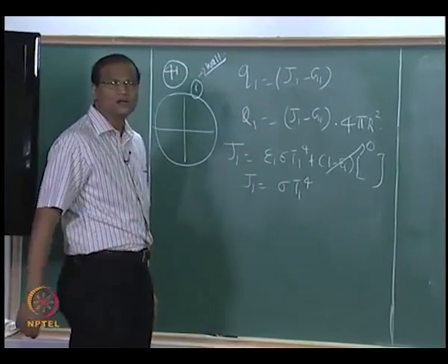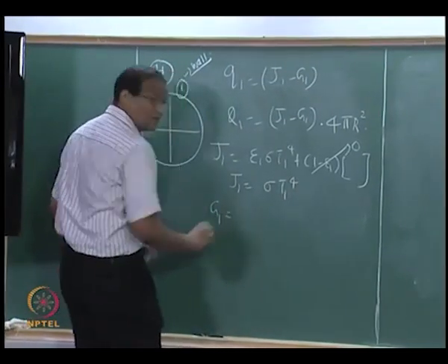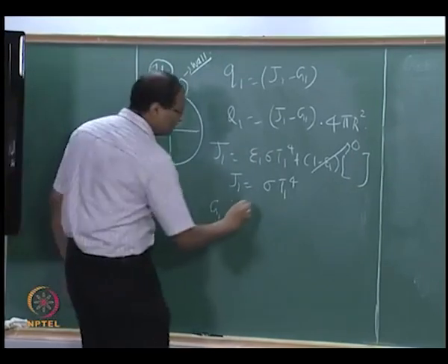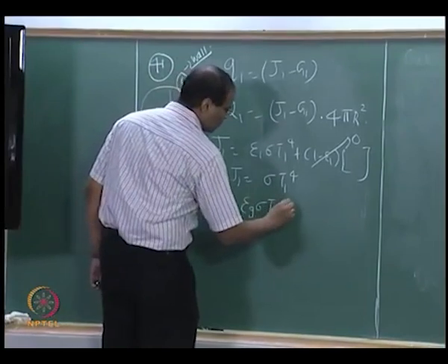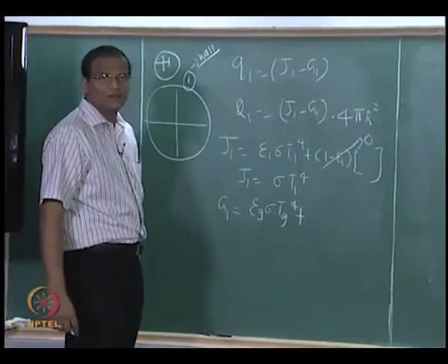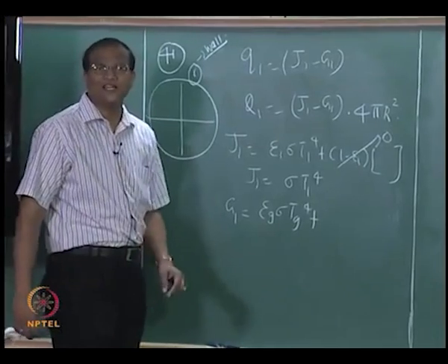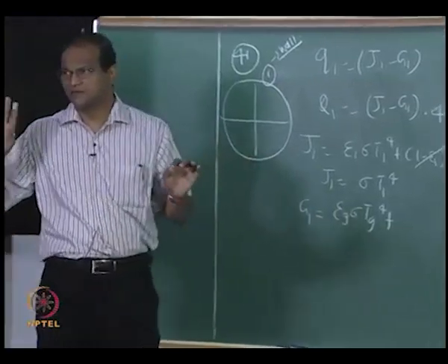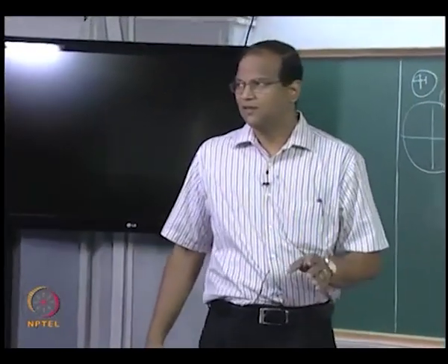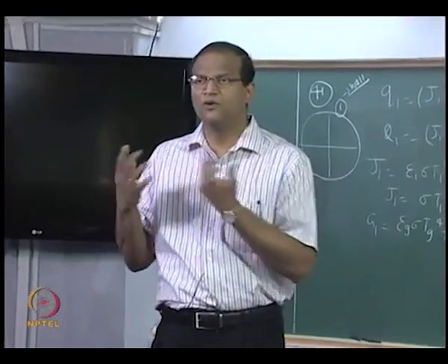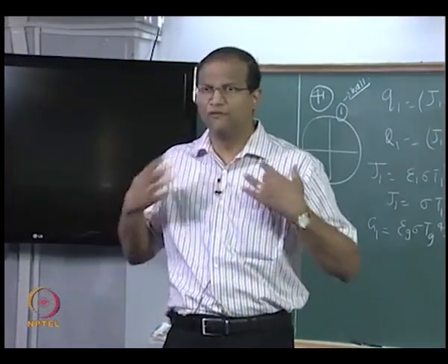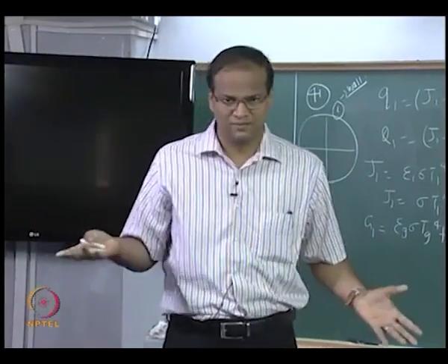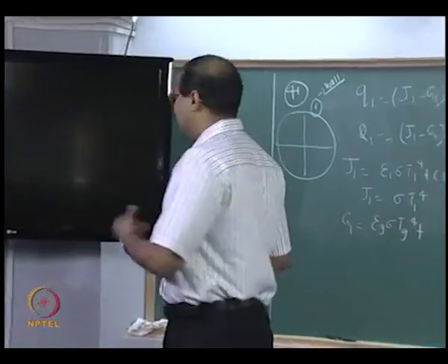Now what is G1? It is gas radiation. Epsilon G, Fij Jj tau Ij. There is only one enclosure. There is only one surface. Okay, the other one is gas. Therefore, F12 is not there. F11 equal to 1. The sphere sees itself fully, and tau 12 can be taken to be tau of the gas. Correct? You can call it as tau G. Therefore, plus